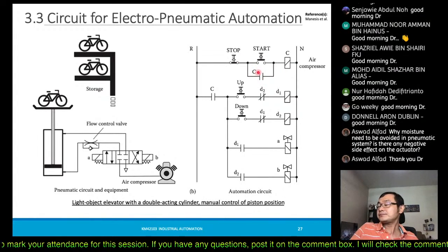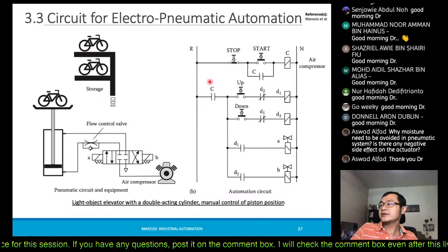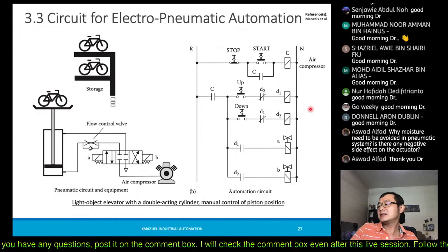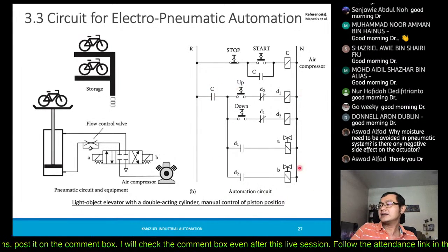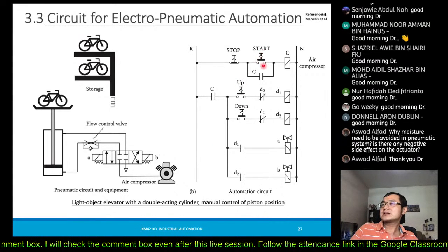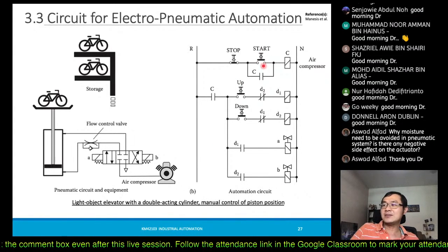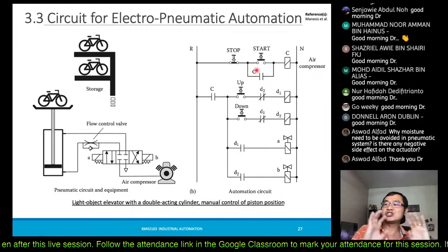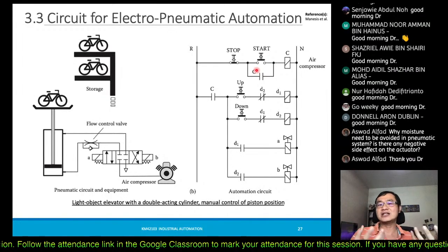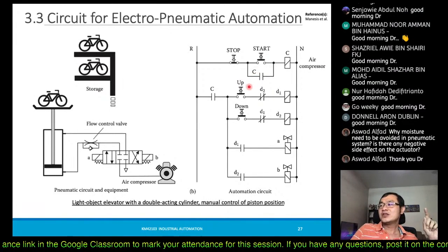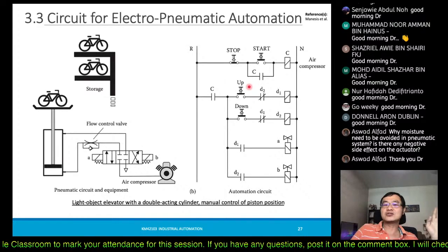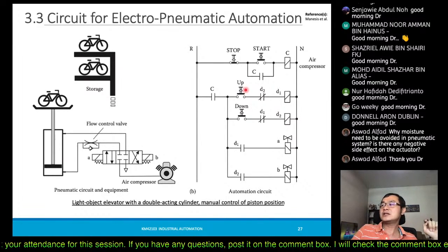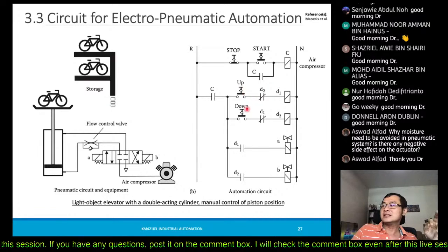So this auxiliary relay now will operate this whole idea. Once you press the start, it may not start immediately. It only tells the machine to be ready to start. Now in order to control the direction, whether it should go up or down, you need to press the desired button.